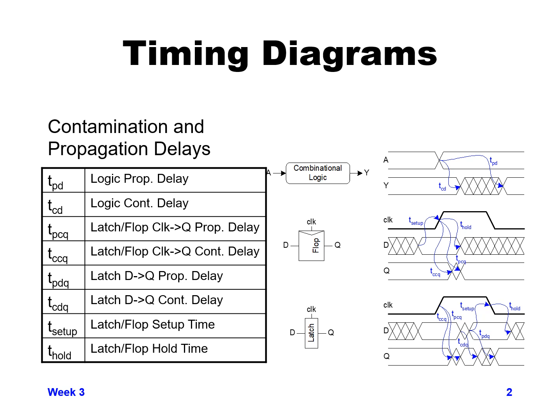For a flop, because you don't have all these different paths of combinational logic going through it, you just have a clock to out, the contamination delay and propagation delay tend to be a lot closer together than they do when you're going through combinational logic.